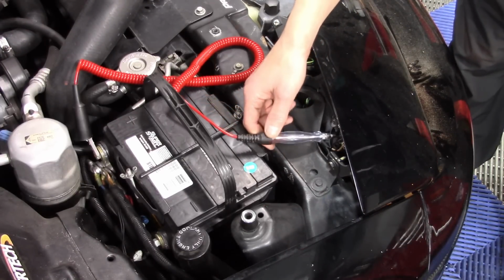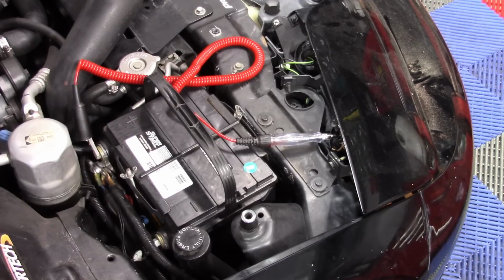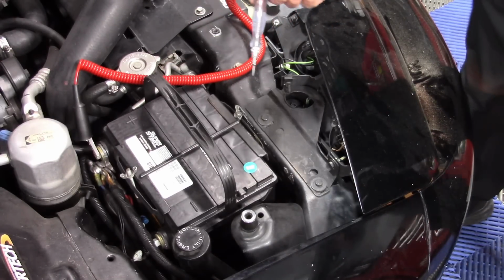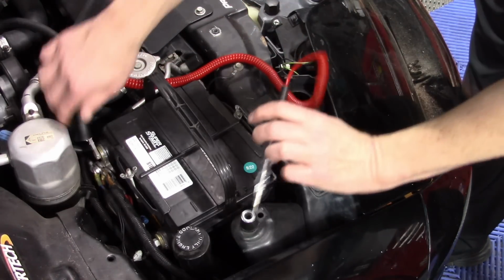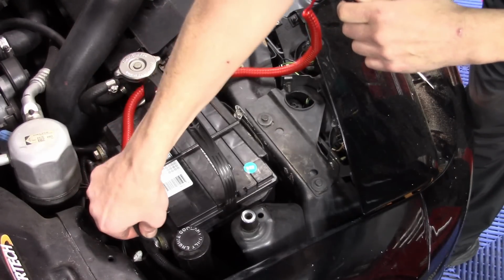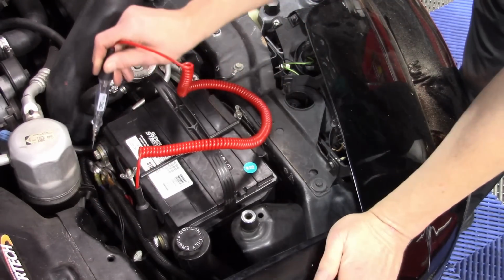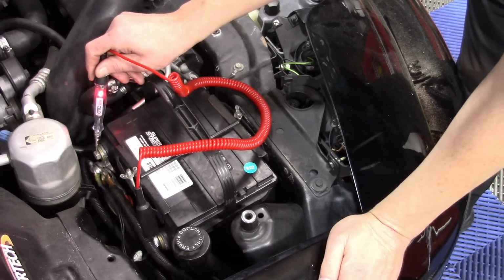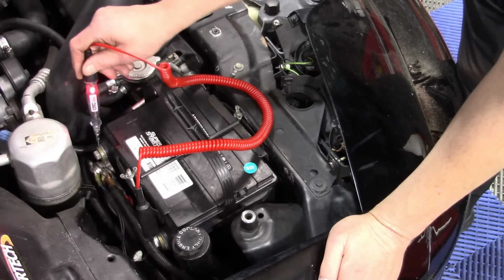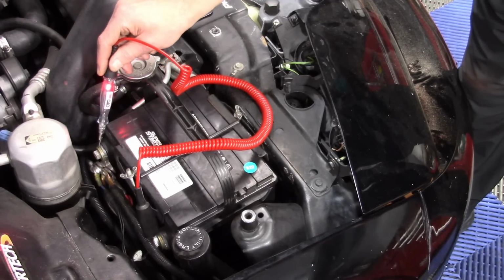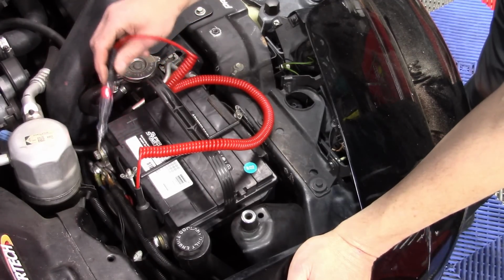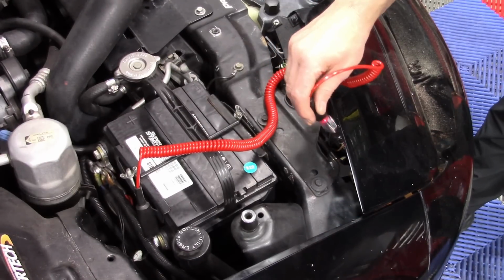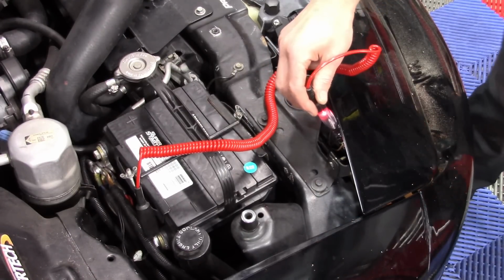Okay, now let me reread these directions just to make sure. It does say it wants me to use the test light to check for a voltage drop. All right, not my favorite thing to do, but what I'm going to do is put my test light over to the negative. We're going to look at the intensity of our test light there because that's our source voltage. That's the brightest that it's going to possibly be, so we're going to kind of memorize that a little bit. We're going to move that over to here, and it should show a little bit dimmer, and maybe it does.